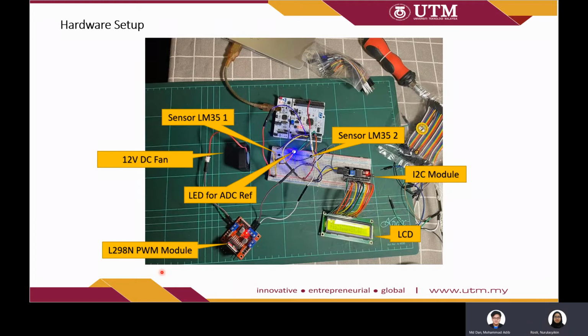Alright, for the hardware setup, this is what our project looks like. We have two LM35 sensors, a 12 volt DC fan, an LED for ADC reference, an L298N PWM module, an I2C module, and lastly an LCD, which all interface with the STM32F4 board. Next is Adib.